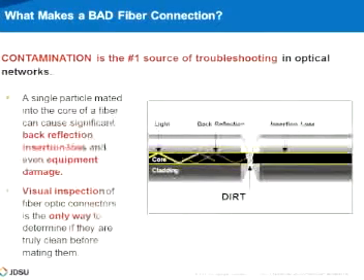A lot of people are trusting the dust caps as the protective interface from contamination. Dust caps are named wrongly. They should be called protective caps, because they are good at physically protecting the interface of the fiber. As much as they can keep the contamination away, they can also keep contamination on the fiber.